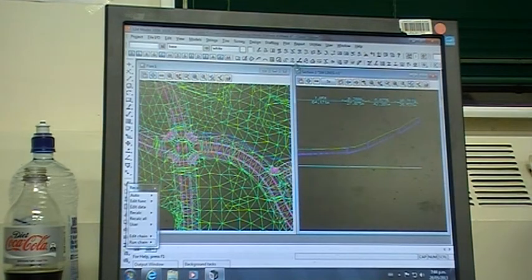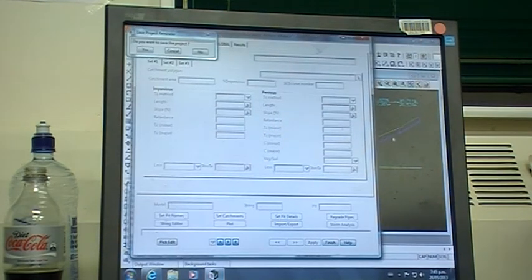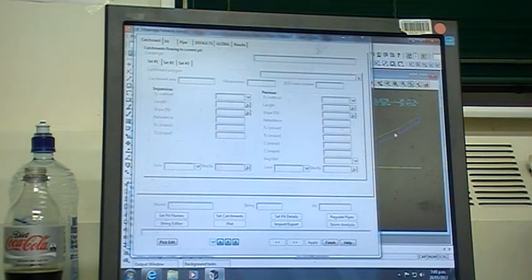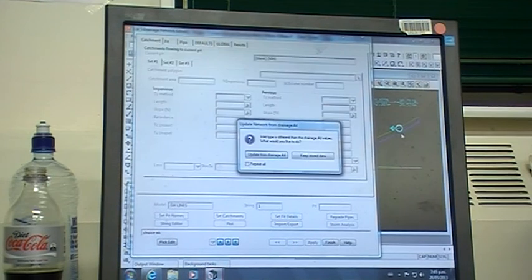All I'm doing is getting to the point where that just disappeared. Here we go. I'll pull that back down so you can see what I'm doing. On the very left hand edge, I have the drainage network editor. I'm going to click on the left hand icon on my drainage toolbar, and I'm going to select stormwater lines number 1 and accept.